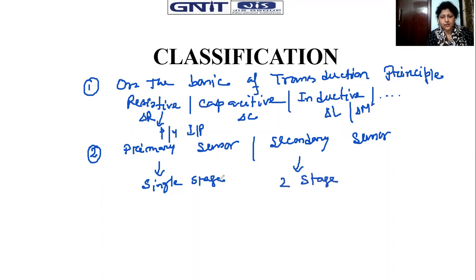So we will go through one kind of, what do we say, LVDT, that will be the example of a particular secondary sensor, or you can say LVDT along with the bourdon tube. The primary sensing unit will be a bourdon tube, and then LVDT will be working as a secondary sensor that will sense basically the pressure as a physical unit.